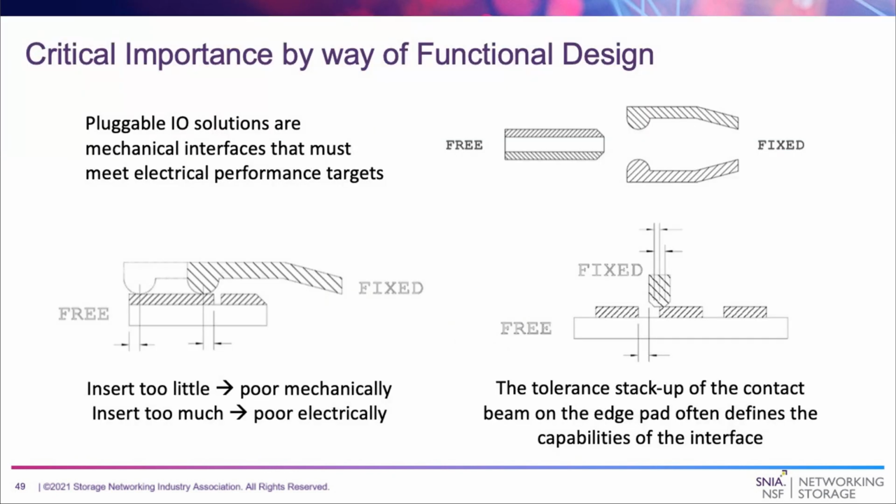So far we've talked about the importance of the interconnect in terms of implementation, either with passive copper or optical examples, as well as application, either long reach or short reach, or switch to switch or switch to server application. But I wanted to change gears a little bit and talk about the importance of the connectors and cables with respect to the structures that make up the interface. The pluggable interfaces are a breakpoint in the data path that must sustain multiple mate and unmate cycles and maintain functionality with multiple supplier solutions intermated.